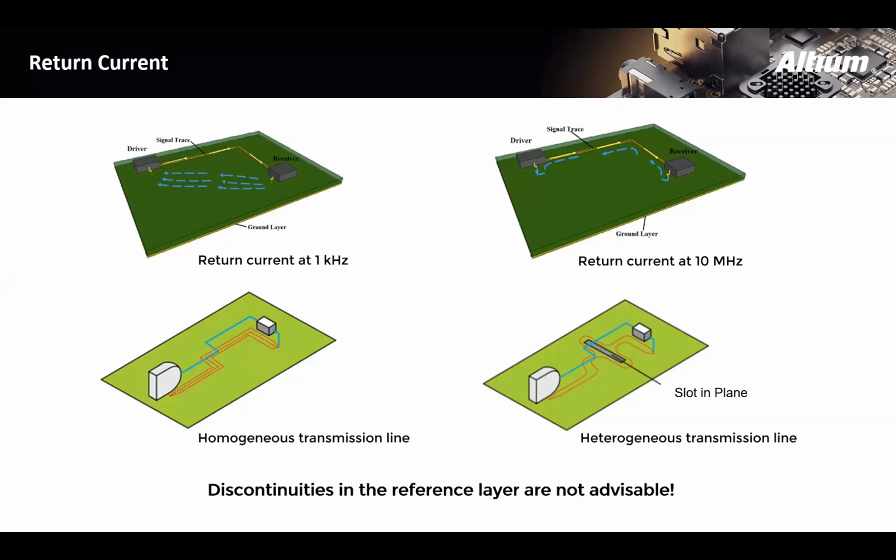And this creates all kinds of issues. For instance, that return route might go over some other signal conductors, and that generates crosstalk. You get all types of reflections in here, and that generates issues trying to get your product or board to pass EMI testing. So you really want to avoid any types of slots or any other discontinuities in the return path. That's a simple mistake I know I've made in the past, which really caused some odd behavior.